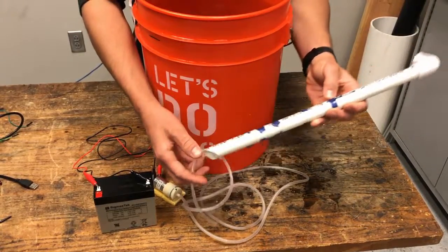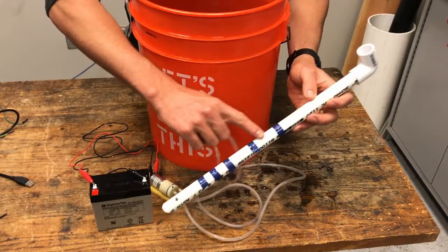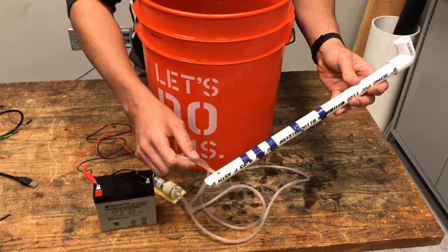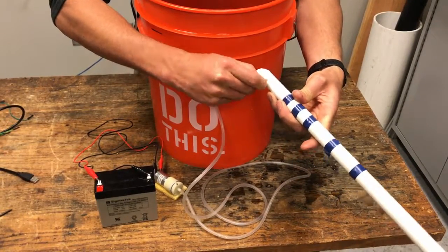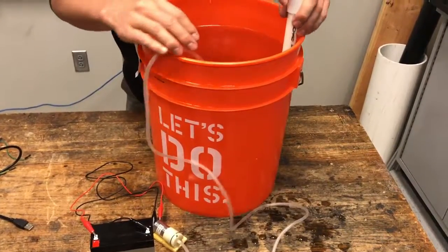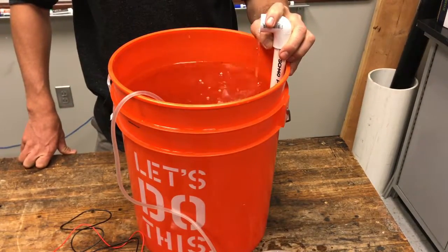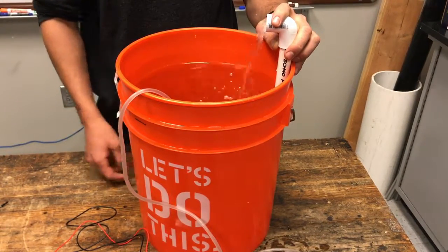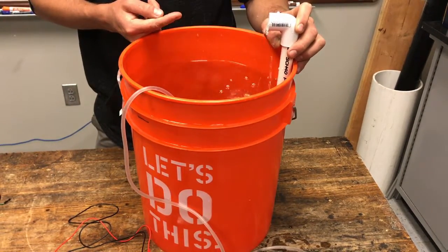And what I have on this tube is a series of holes to demonstrate how the flow rate changes when we have a different ratio in the depth underneath the water to the head above the water. So if we start at the very bottom, we insert the airflow here. Then we're just going to go ahead and set this at the bottom of the water. So right now, this is about 3.5 inches of height above the top of the water line and 14.5 below the water. This gives us about 30 gallons a minute of flow.